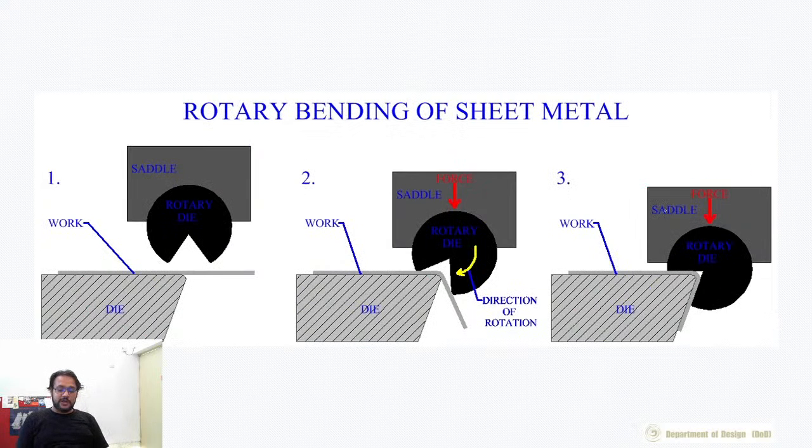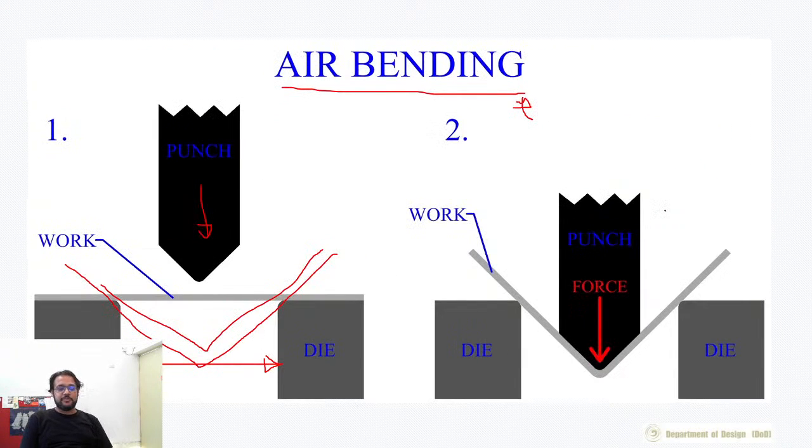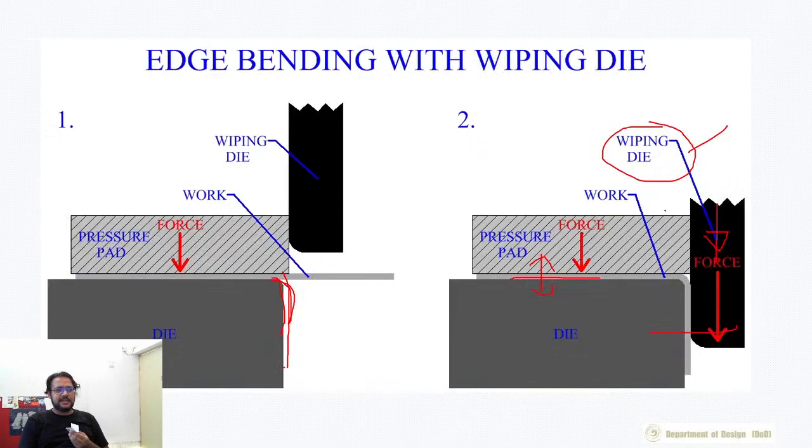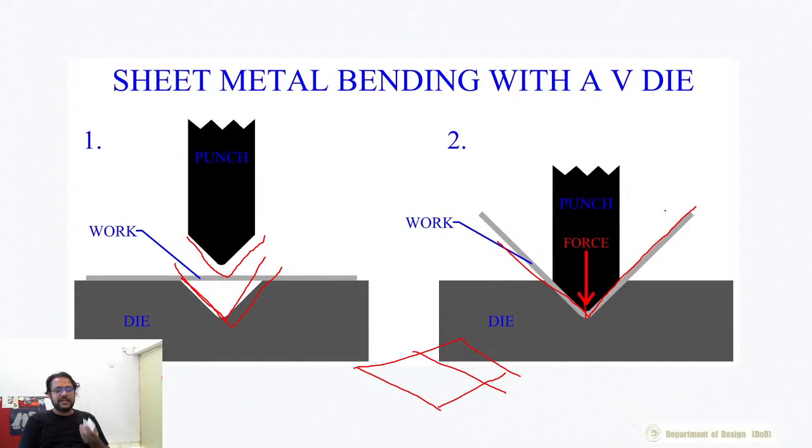One of the main problems for these kind of processes, so even for air bending, you could do an acute bend, you could bend it to a much larger angle, but let's say for something like this, it becomes quite difficult. As and when you keep approaching certain kinds of angles, you would find it difficult to control the punch because it becomes thinner and thinner, right? So getting a very sharp bend becomes difficult.